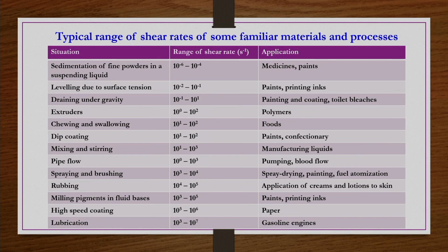So now if you have a situation like sedimentation of fine powders in a suspending liquid, such kind of applications we see in medicines and paints, and the shear rate is very small, of the order of 10 power minus 6 to 10 power minus 4 second inverse. We have leveling due to surface tension, that kind of situation in paints and printing inks applications. There the shear rate is of the order of 10 power minus 2 to minus 1.